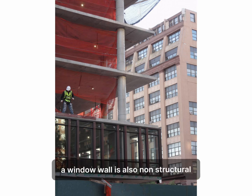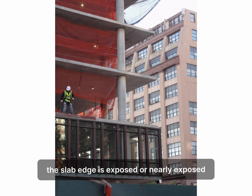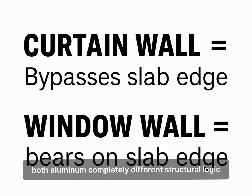A window wall is also non-structural, but it bears on the slab edge below and is captured by the slab edge above. The slab is the support. The slab edge is exposed, or nearly exposed, on the exterior. Two systems, both glass, both aluminum. Completely different structural logic.